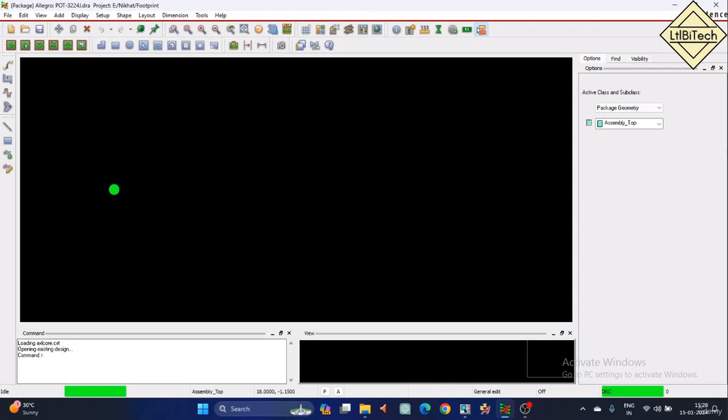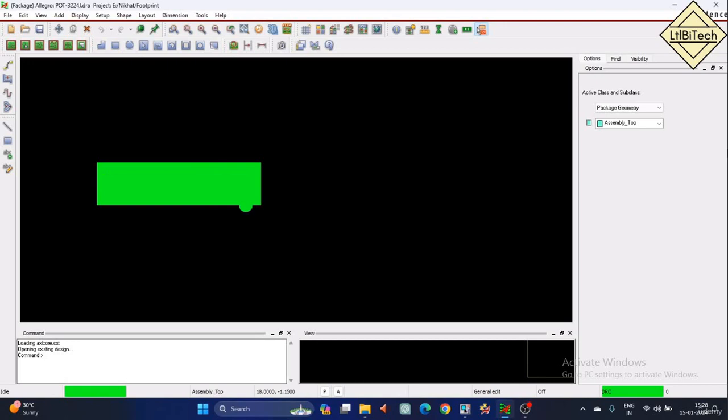These thicknesses are subject to change with the manufacturing. So for any PCB stack-up, I request you to contact your manufacturer so that they will give you the right datasheet or the right document about the PCB thickness, core thickness, copper thickness, or prepreg thickness.